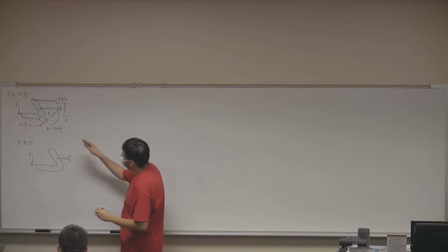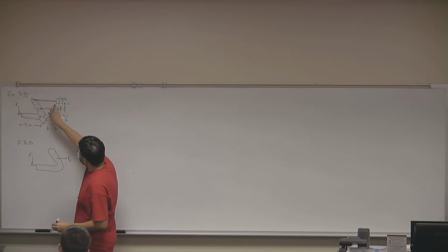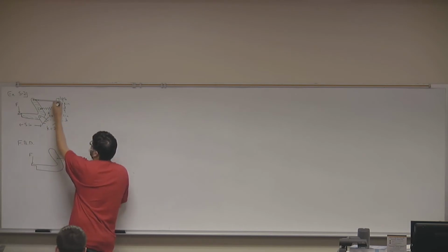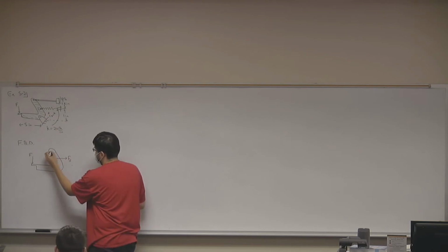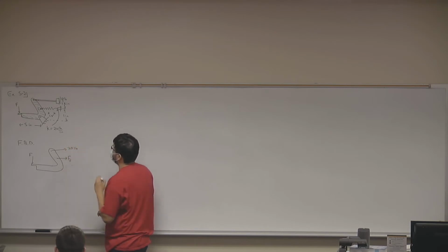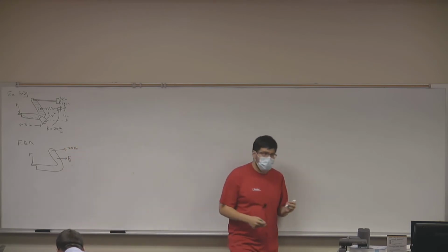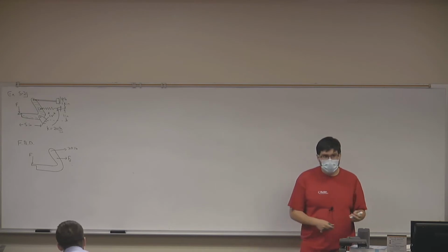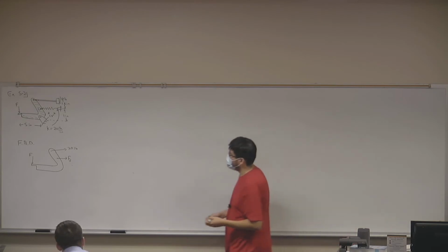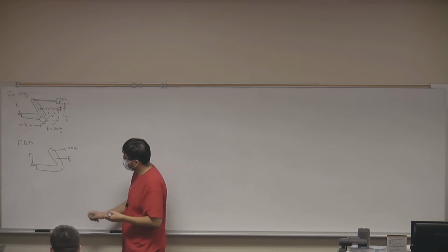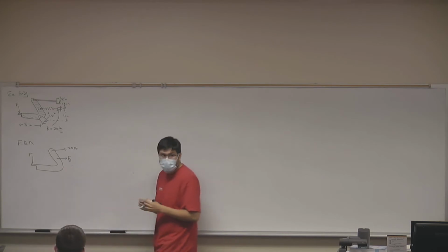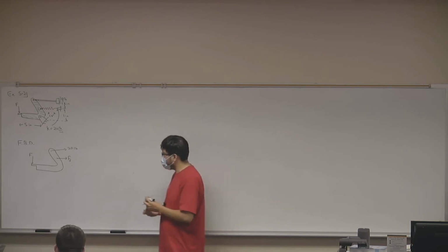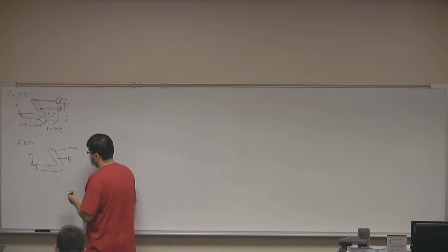We mentioned that when you press on this pedal, this link, let's say that it's also fixed or somewhat fixed, will exert a force of 20 pounds. Okay? So we have a force from the link of 20 pounds. Sophia, are those all the forces acting on the system? No, there's also the hinge. All right, where? The bottom right. Okay. And what reactions does this hinge provide? X and Y. Okay. An X and Y reaction force.